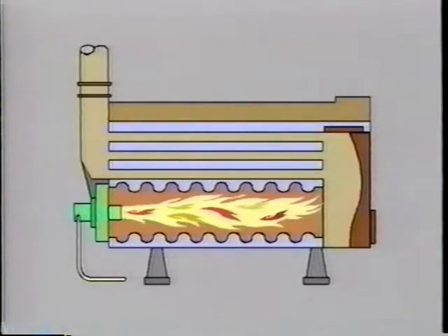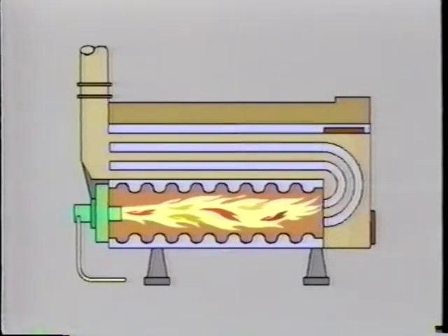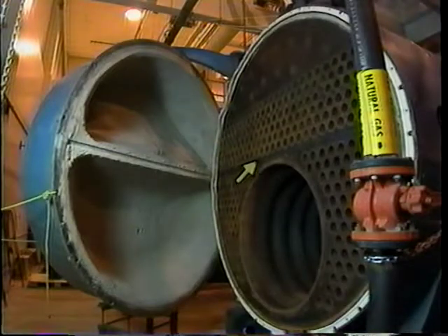Fire tube boilers are available as either dryback or wetback boilers. In a dryback boiler, a refractory lined chamber outside of the vessel directs the gases of combustion from the furnace to the tubes. In a wetback fire tube boiler, a water-cooled turnaround chamber directs gases of combustion from the furnace to the tube bank. A tube bank is an assembly of tubes in the boiler.